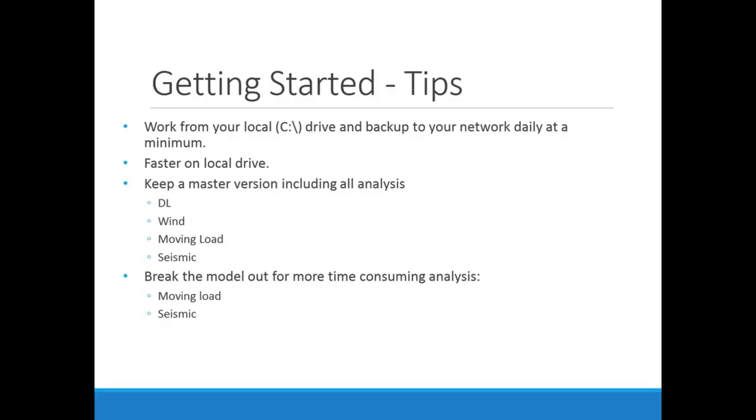Also, it's good practice to always keep a master version of your analysis, and this includes everything that's in your model. You're including all of your dead load, your live load, your wind loading if that's something specific, and seismic loading. That way you have everything all in one place, and you make sure that that's always the most up-to-date version. And then from there you can always break off and create other versions. Specifically, you're going to want to break out your model for moving load analysis or seismic analysis.